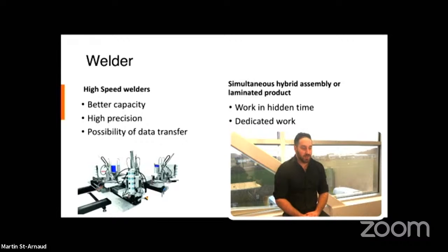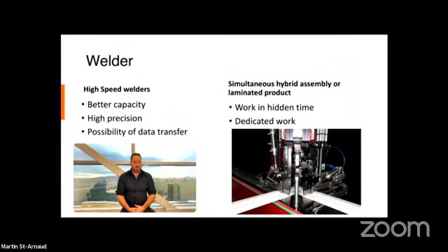Another thing that you can do on the welder now, you could have a drill that's been installed between two heads to do your mullion post on your frame. So the 3-head drill only applies to casement frames. But if you do have a welder that's dedicated to casement frames, this could be a good add-on as you're positioning your mullion as the window is assembled and being held at a square inside the welder, so you know that the precision is going to be 100% at that point.